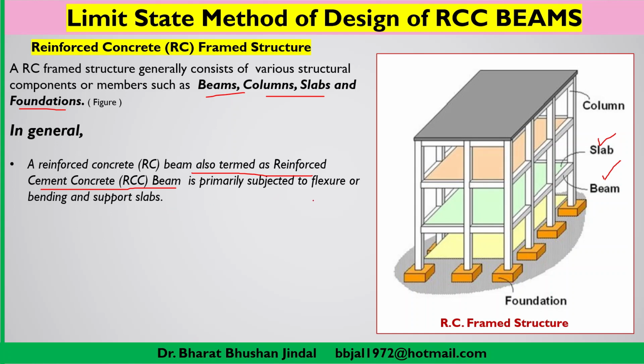A very important aspect of a beam is that primarily it is subjected to flexure. Flexure means bending, and it is supporting the slab. As you know, a column is generally considered a compression member. It will be subjected to compressive forces, and depending upon the location of the load, whether it is along the axis of the column or has some eccentricity, some bending may also occur. In case of an RCC beam, we generally consider that it will be subjected to bending, that is, it will be under flexure. That is a very important aspect of today's lecture: we have to discuss the behavior of any beam under flexure.